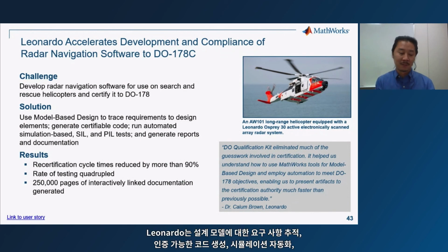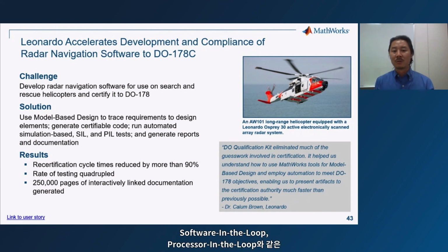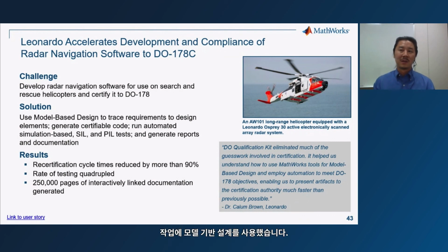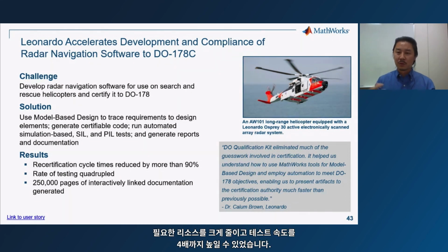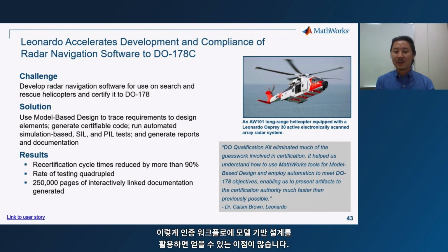And they used model-based design for tasks such as tracing requirements to the design model, generating certifiable code, automating the simulations, software in the loop, processor in the loop simulation tests as well. And then finally, generating the many reports needed for this certification effort, right? And through using model-based design, they were able to vastly reduce the resources needed to go through this certification and recertification cycle as well. And even quadrupled the rate of testing here, right? So a lot of great benefits seen here from utilizing model-based design for certification workflows.